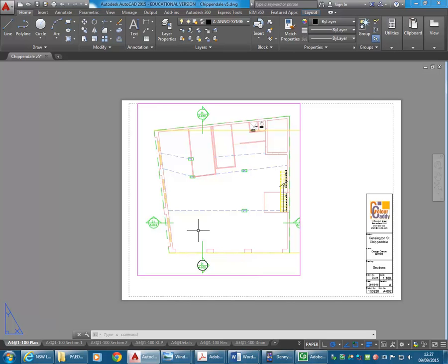And that's standard for as existing drawings. You don't need to give measurements because the walls and the other things aren't changing anytime soon. They're as they are, and so you just need to indicate those on your drawings so that when you dimension your new work with measurements, the builders know to go and find the wall that you've drawn nice and accurately and then measure from there. And there's also a bit of a convention that if something's dimensioned, that it's meant to be built. So you really should only give measurements for new things most of the time.